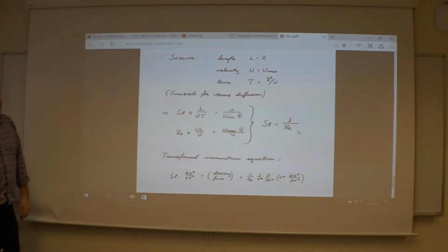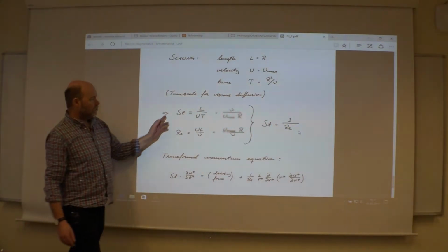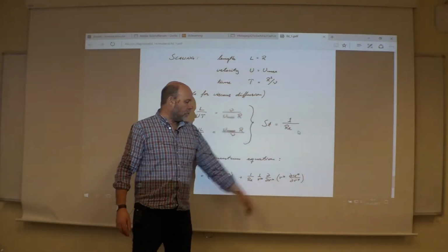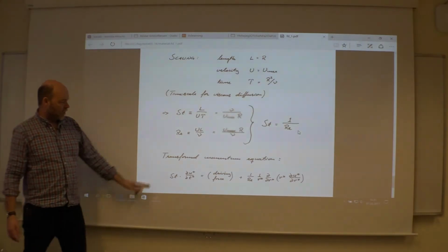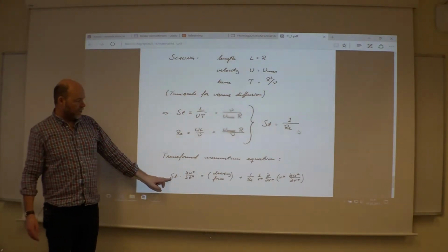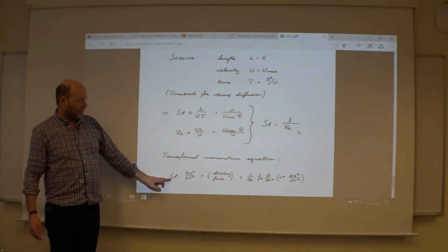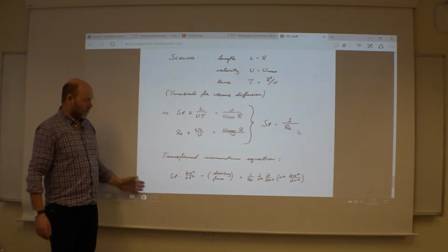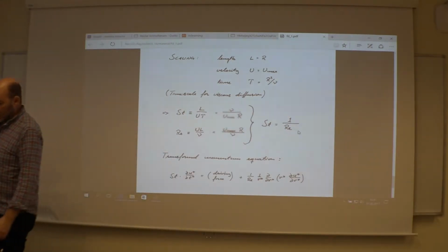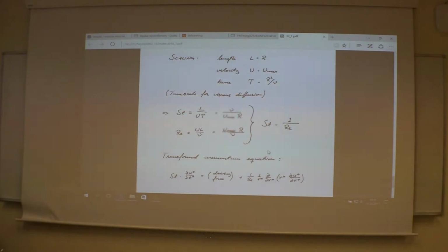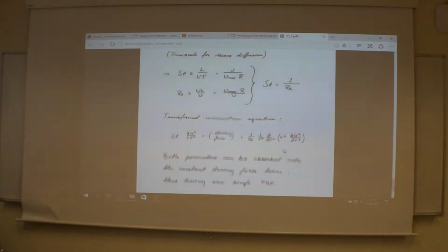Now, if we choose this viscous time scale, you also see the Strouhal number actually becomes 1 over the Reynolds number. So that means we will have 1 over Reynolds number here as well. So that's fairly neat when you then write it without dimensions, multiplying with the Reynolds number, that then will enter into the driving force into the equation.